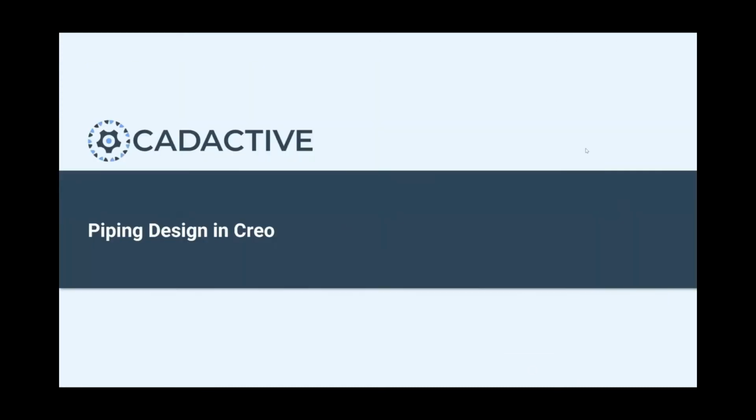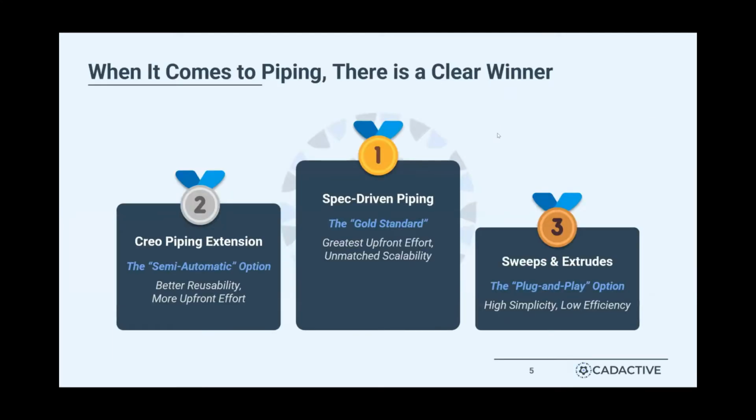Cool. So let's get into piping design in Creo. To start, I just wanted to give a really high-level overview of the different options that are available for piping design in Creo. And when I say piping, I could mean rigid pipe, flexible tube, HVAC, waveguide, really anything that you route. But across all of those, there are really three ways to route pipes in Creo. Number three, sweeps and extrudes. Number two, using the piping module, the piping and cabling extension. And number one, spec-driven piping, which is really what we're here to talk about today.